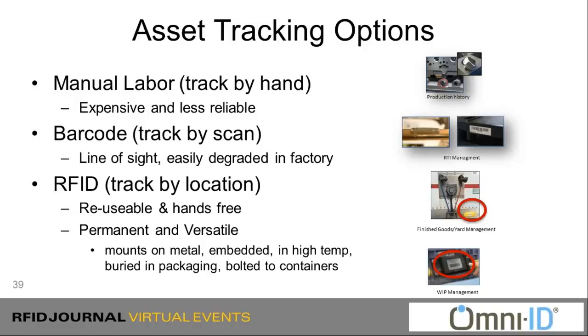RFID, as Mark said, is gaining traction in manufacturing, but to be honest, we're surprised at how slow it's been. RFID adoption, while there are lots of small islands of it being used, hasn't been pervasive. The advantage of RFID, of course, is that it's reusable and hands-free. You don't have to worry about any kind of marring of the tag like you do in barcoding, and you don't have to have an operator pick up a scanner to go get it. You can have antennas permanently mounted. That's a huge advantage for your process flows.